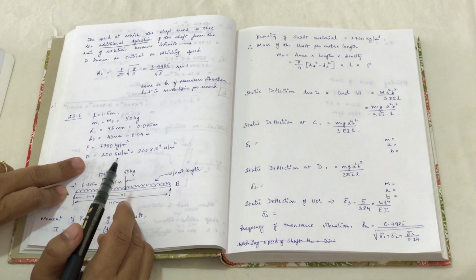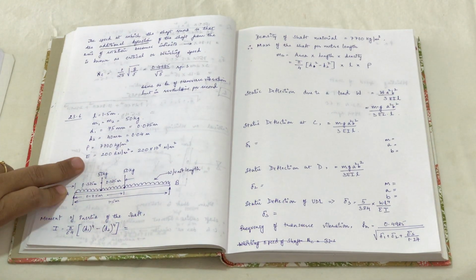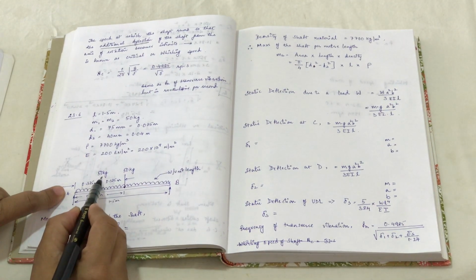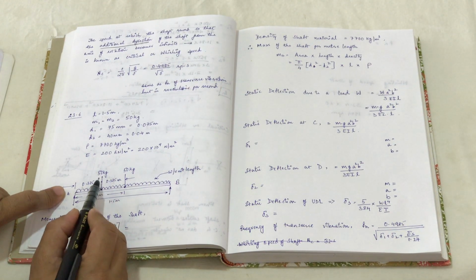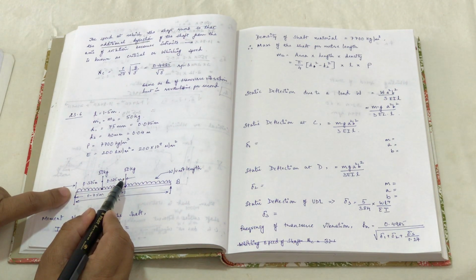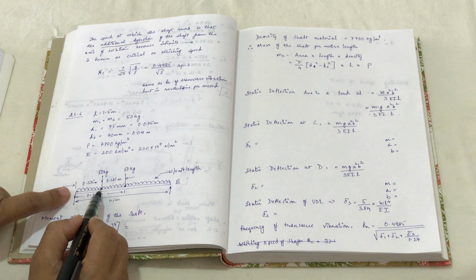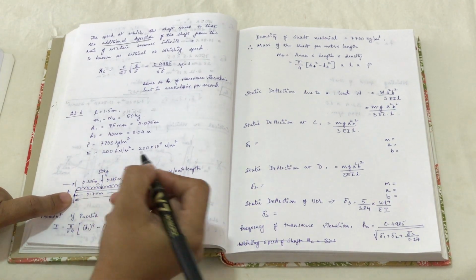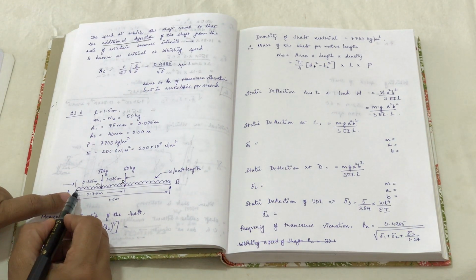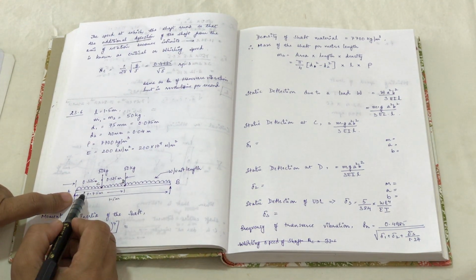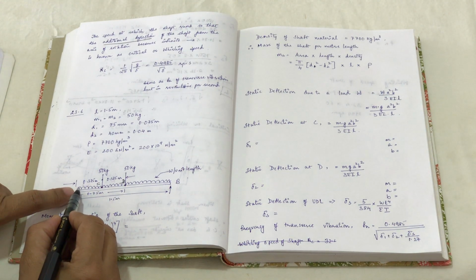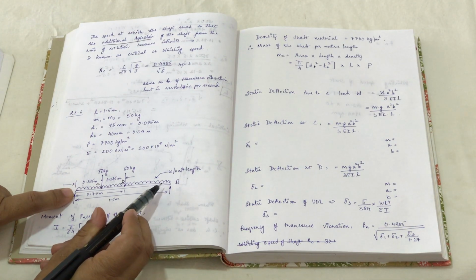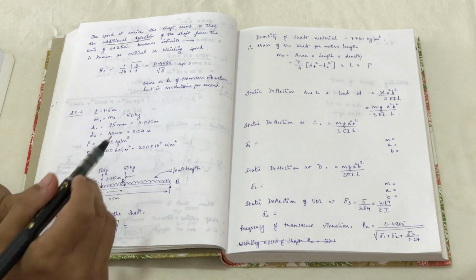So the question says calculate the whirling speed considering the weight of the shaft. So there are 2 point loads, that is the wheels, 50 kg and 50 kg, acting at the midpoint and at another point. I'm going to name those points C and D, which will be easier to explain. And we need to consider the weight of the shaft. So it's a uniformly distributed load, so you can add a uniformly distributed load throughout the length, denoting the weight of the shaft.